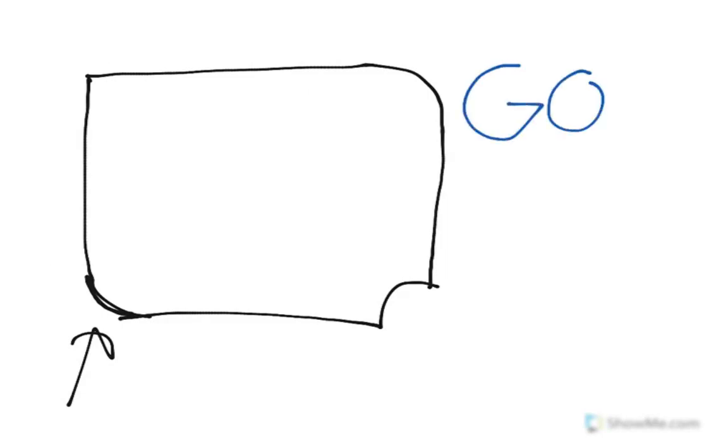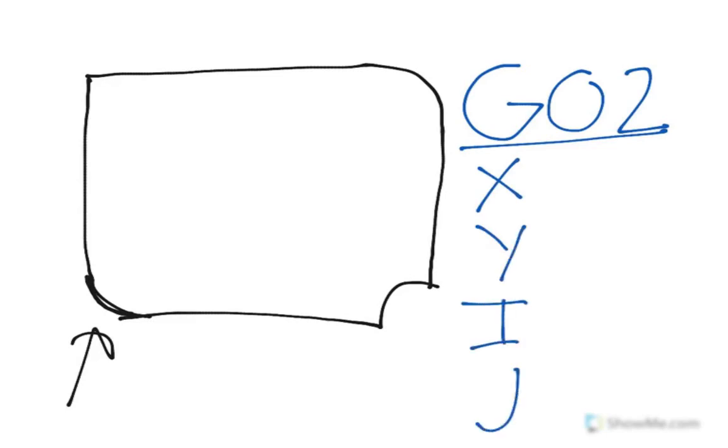After that, just like before, we moved across, moved down, moved around, moved over here, and now we need to do the final piece here, which again is another rotation. Now we specify that with the G02, so we have a rotation. We need an x, a y, an I, and a j.